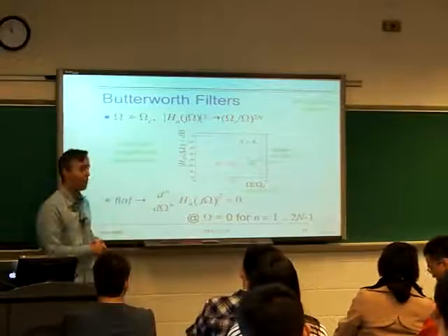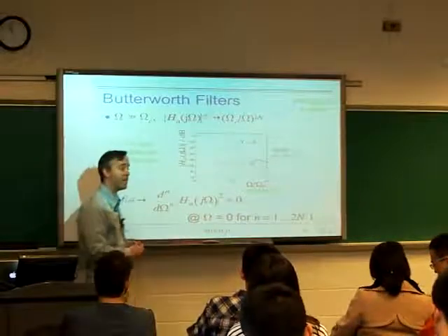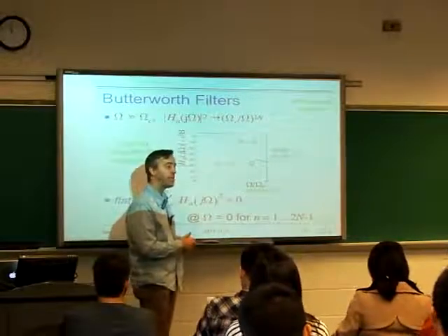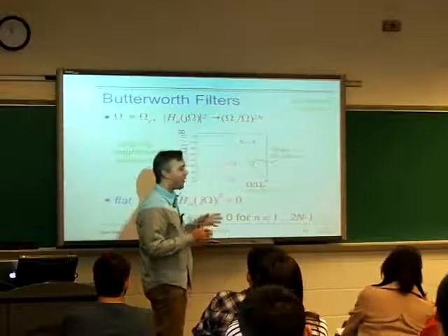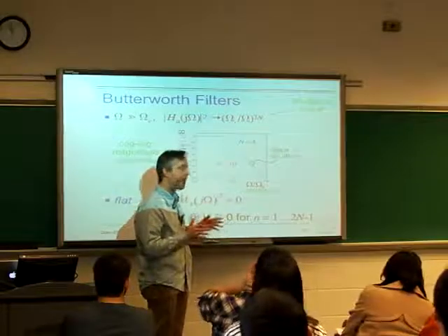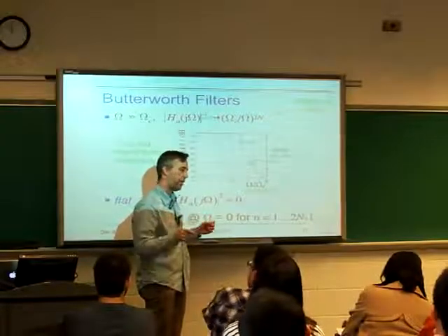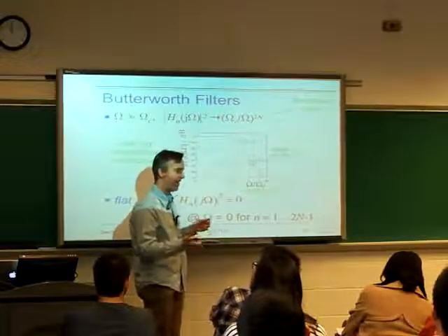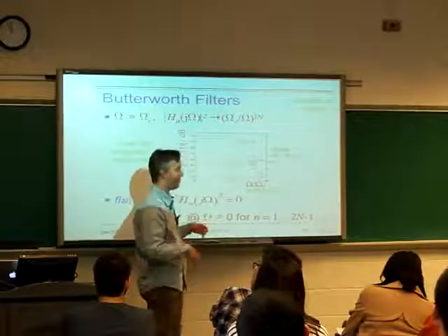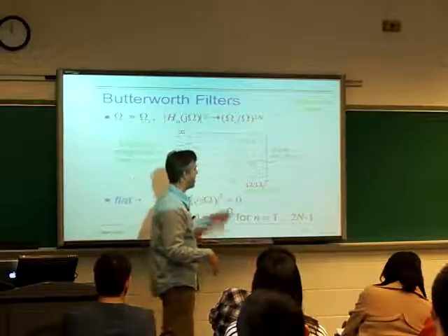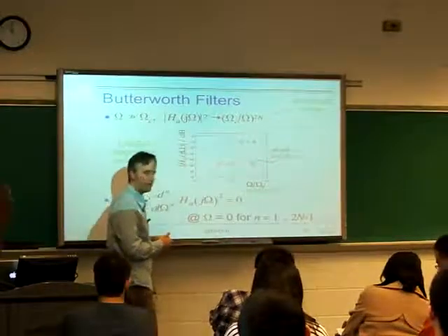So, if you've worked in analog design, you're used to seeing that kind of thing. Yeah? Where does that come from again? Oh, so the log base 10 of 2 is 0.30103. So 20 times the log base 10 of 2 is 6.0206, which we approximate as 6, and so that's the 6 dB per octave.